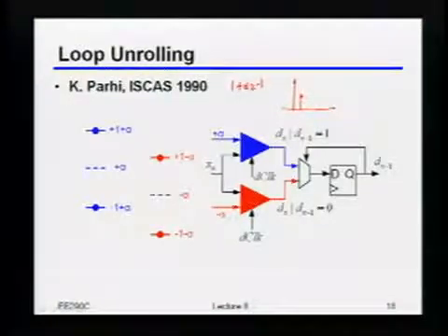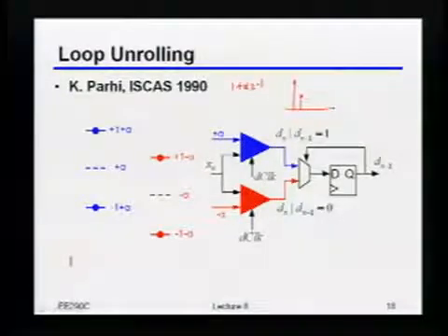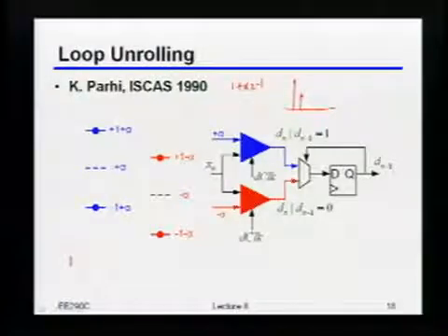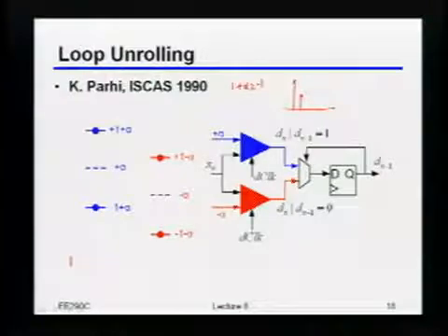The idea here is a lot like a carry look-ahead adder, in the sense that we'll assume that we knew the previous bit was a 1, or assume that we knew the previous bit was a 0. In either one of those cases, I could statically shift the threshold of the comparator to eliminate the ISI that those two cases would have seen.